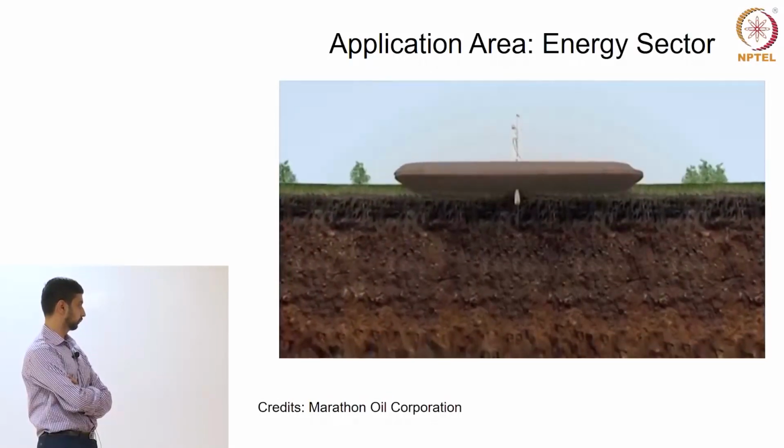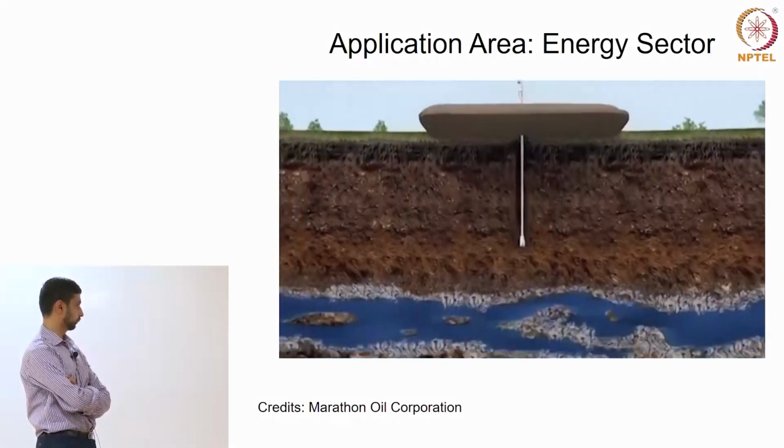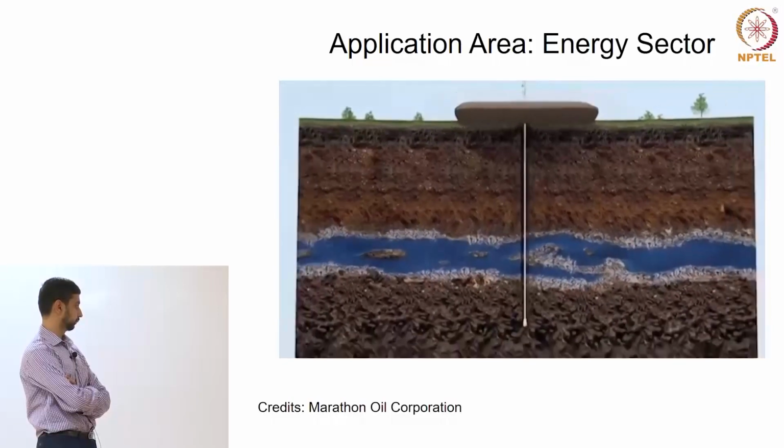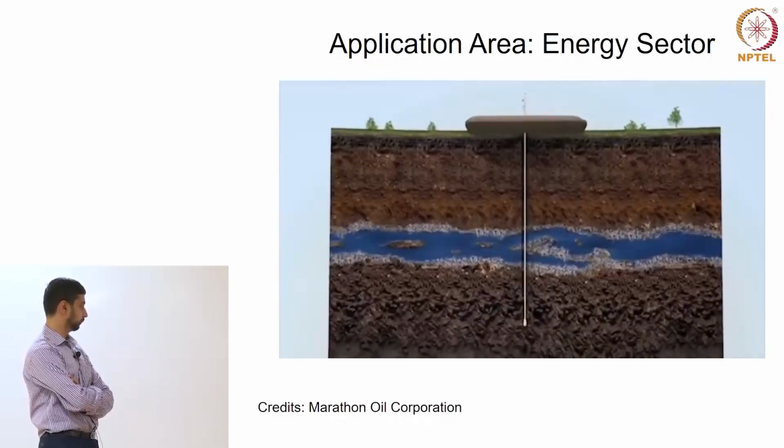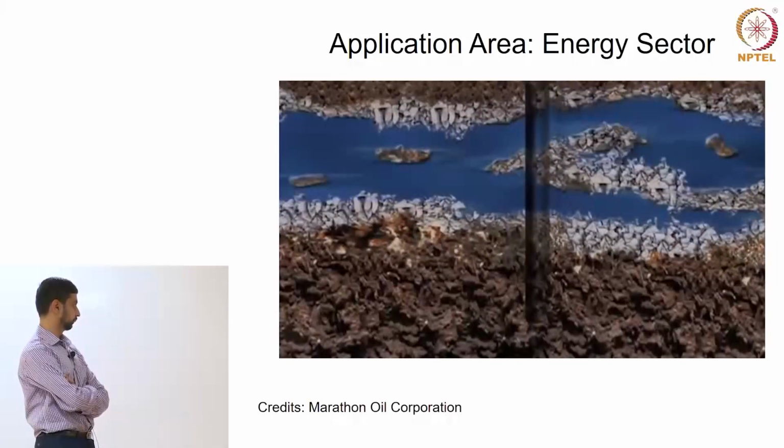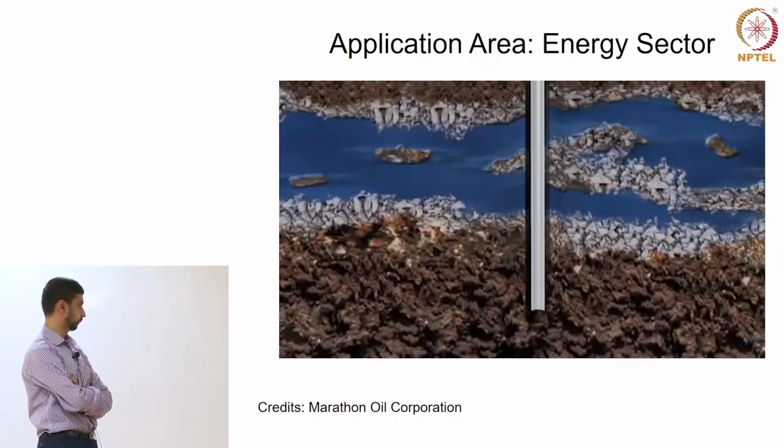The initial steps are the same as for any conventional well. A hole is drilled straight down using freshwater-based fluids, which cool the drill bit, carry the rock cuttings back to the surface, and stabilize the wall of the wellbore. Once the hole extends below the deepest freshwater aquifer, the drill pipe is removed and replaced with steel pipe, called surface casing. Next, cement is pumped down the casing.